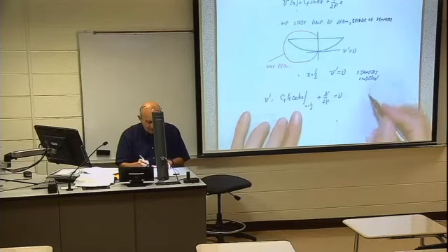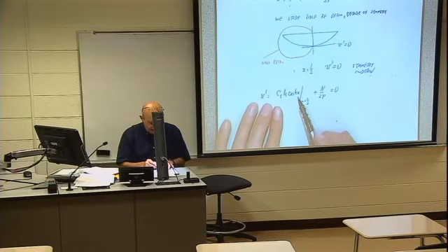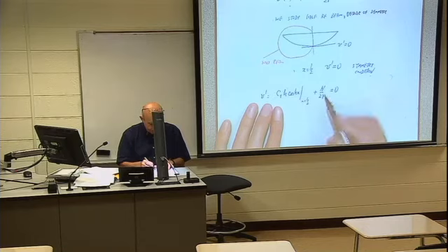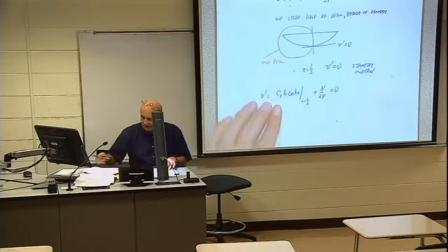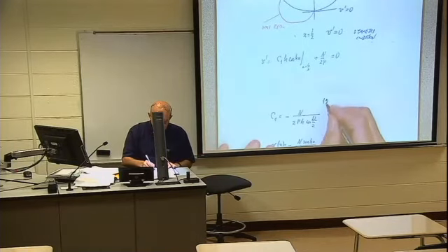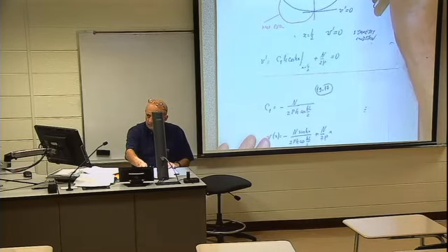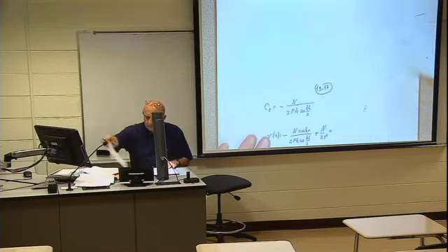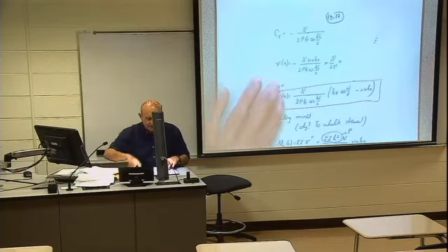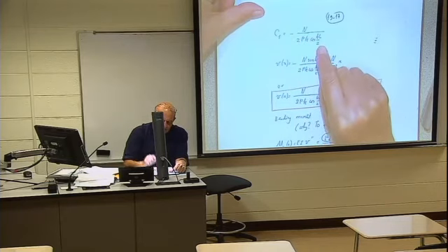Symmetry condition. So V prime equals C1 k cosine kx plus n over 2P, that is the first derivative, equals 0. So C1 equals minus n over 2Pk cosine kL over 2.